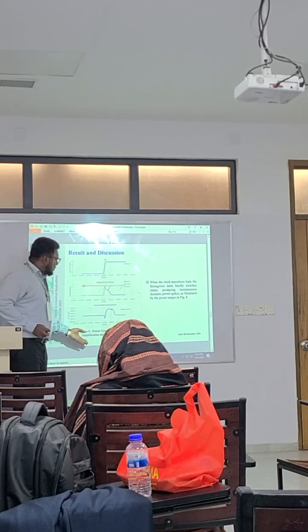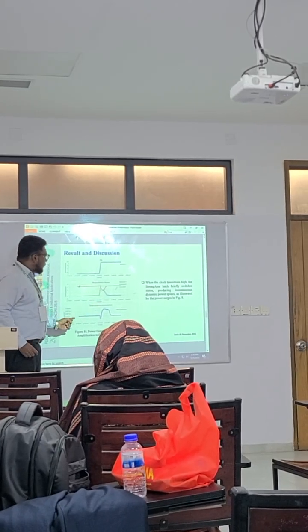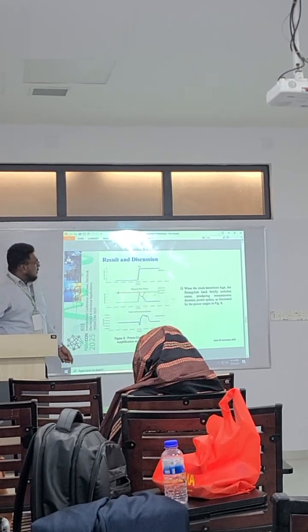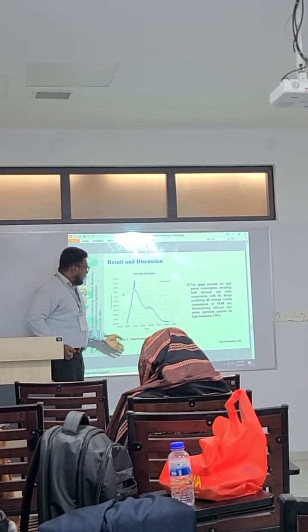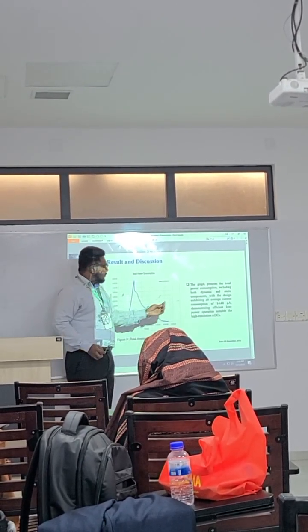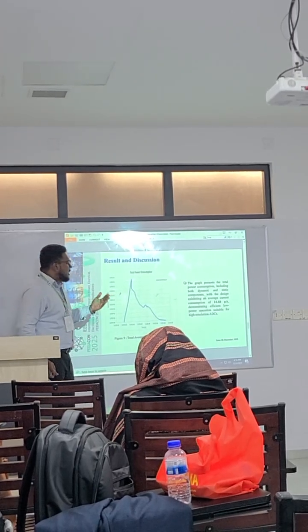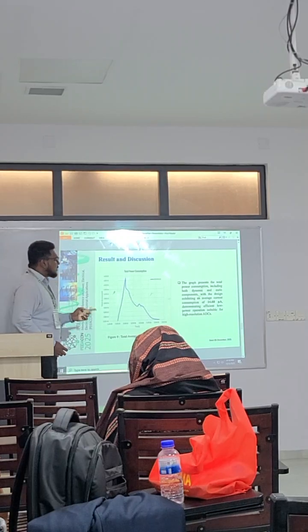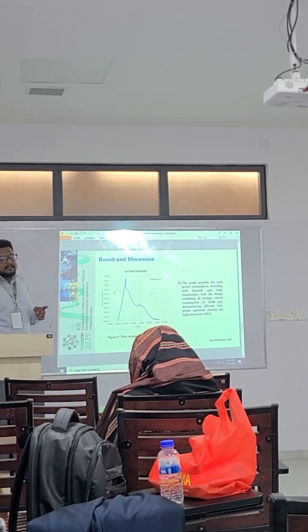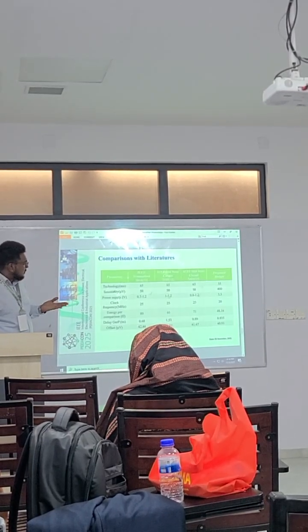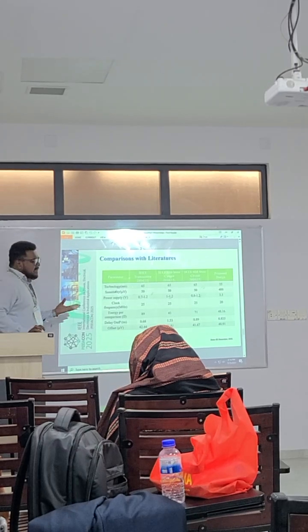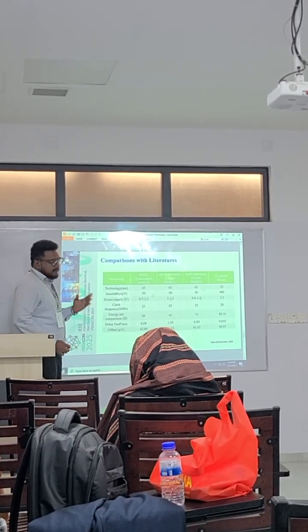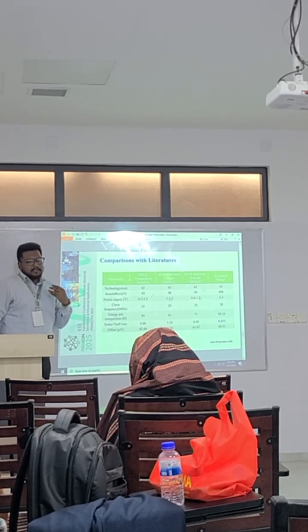This is the power consumption. So whenever there is a regenerative action, we can see an instantaneous dynamic power spike. And this is the total power consumption, which includes both the dynamic and static components. So basically, it exhibits an average current consumption of 14.60 microampere, which tells us that it is a low power consuming device. So here's a comparison table with the established work of this circuitry.